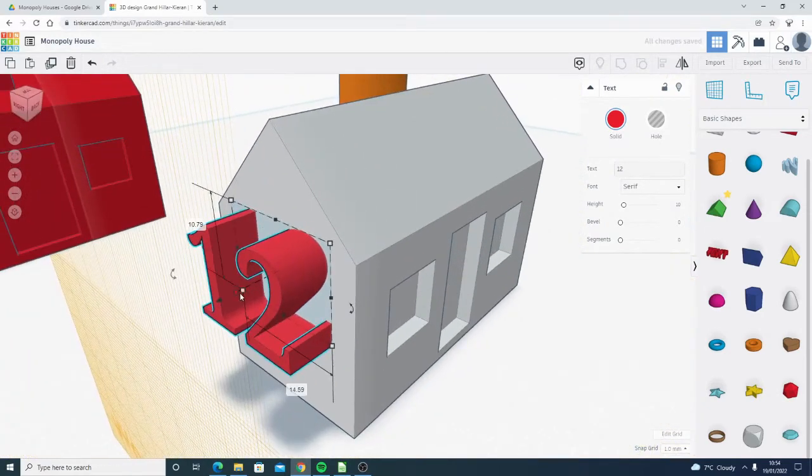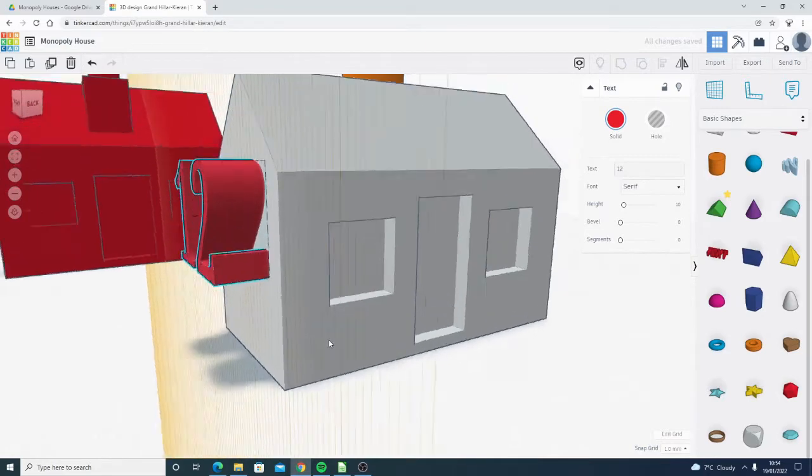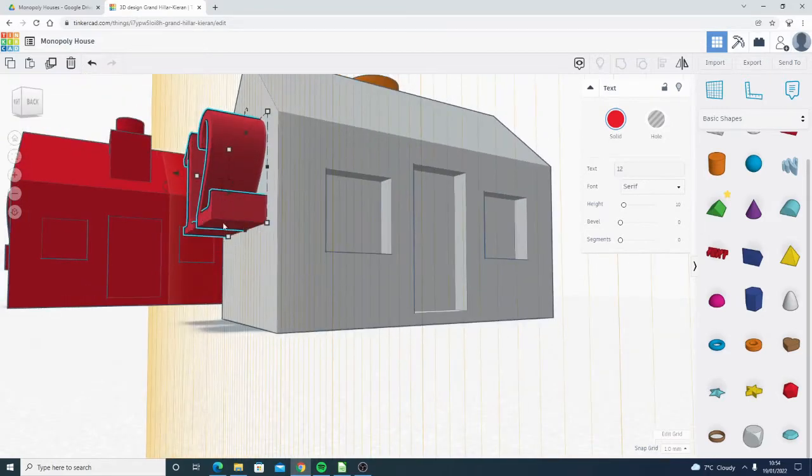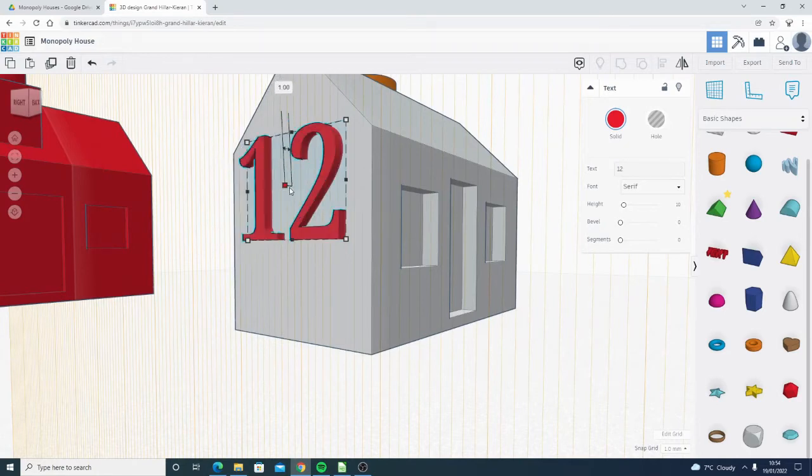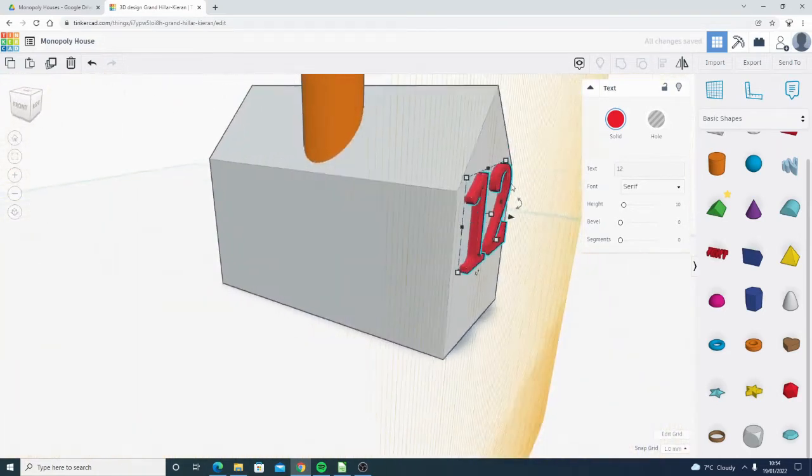Now at the moment, this one is poking out of the face, and it will handle about 1 millimeter sort of overhangs quite happily. Like this. So at the moment, you have problems trying to print this. It won't, because it'll be trying to print in thin air here. So let's shrink that so it's about 1 millimeter thick. So that would be fine, it would manage that.